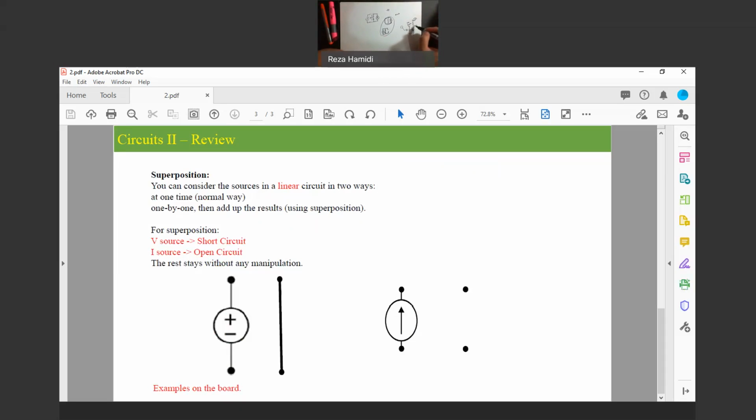If you have a look at this circuit, without having this one, just this is kind of a source. When someone speaks here, that vibrations generate a small voltage, and that small voltage passes through that capacitor, reaches this one, and this one amplifies that. In order to analyze this kind of circuits, people first turn off this source. Using the sources connected to the circuit, they analyze the circuit.